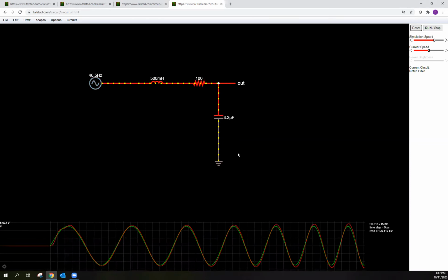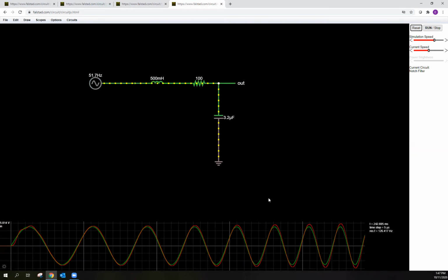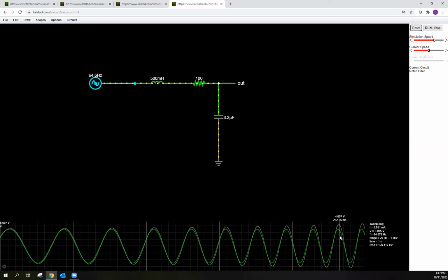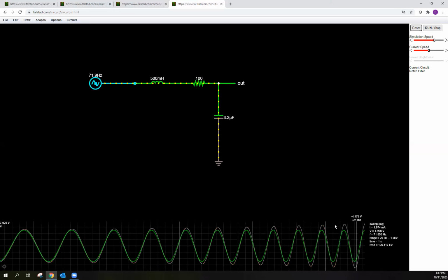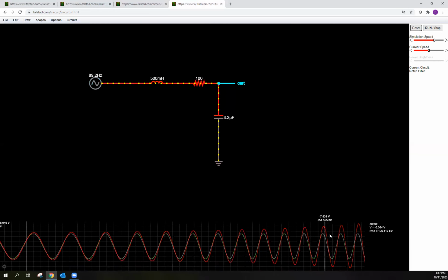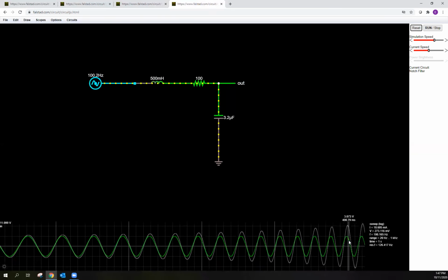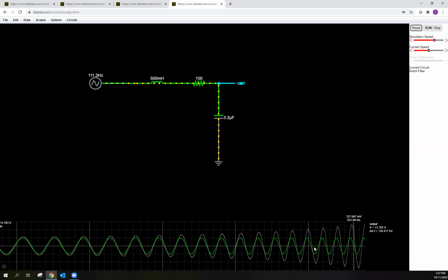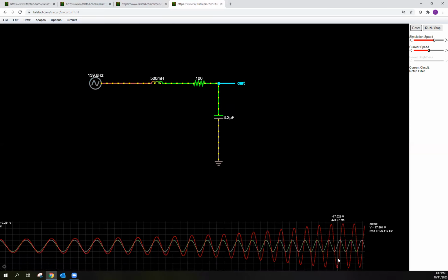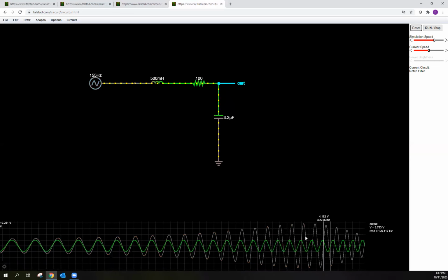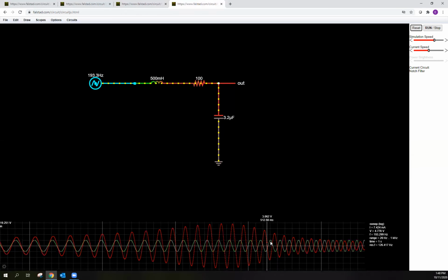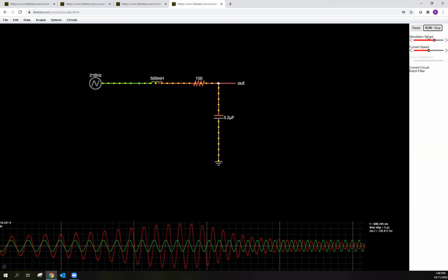So notice what's happening as this increases. What do we got going on? Instead of the output decreasing in amplitude, it's increasing in amplitude. It's starting to hit resonance and the phase is starting to lag, right? Notice the phase is lagging, getting closer. It's going to get as much as 180 out of phase. Look at this, increasing to higher and higher frequency. This is awesome. This is not good, right? Imagine this is a vehicle suspension. So at this point, this is the resonant frequency. And if you start increasing the frequency any further, what happens?